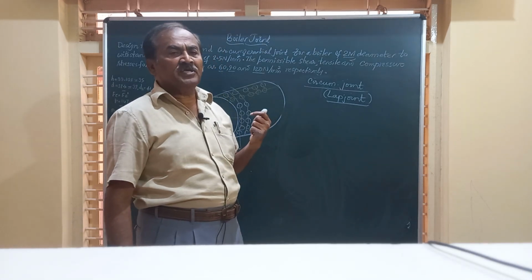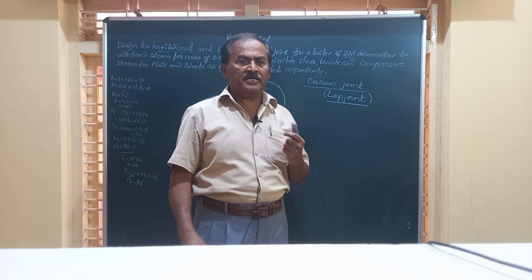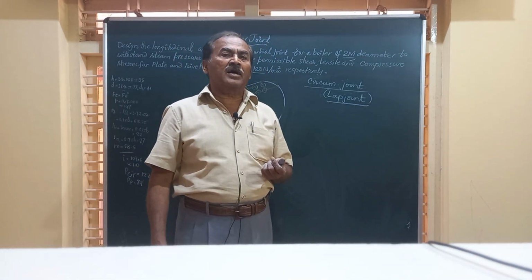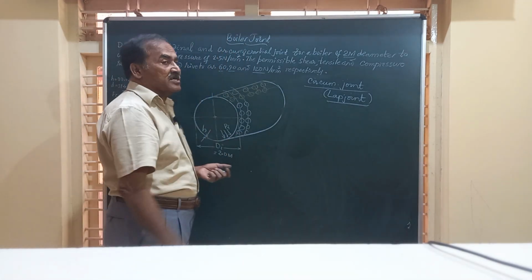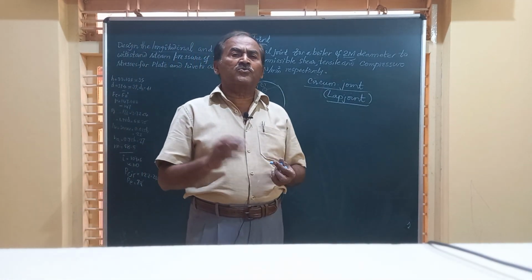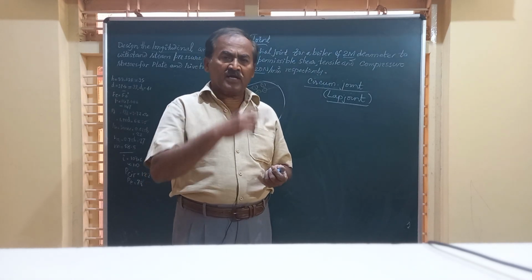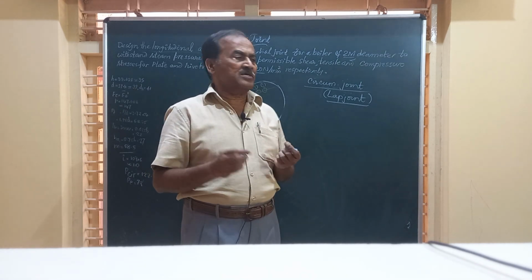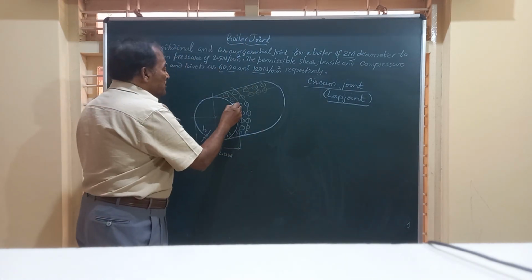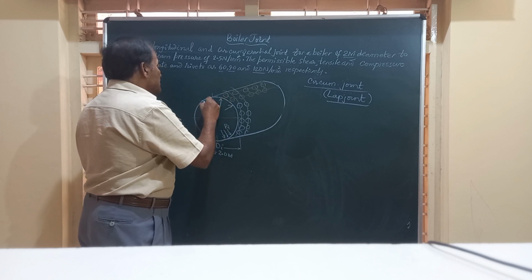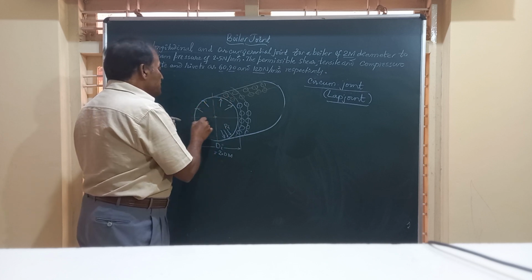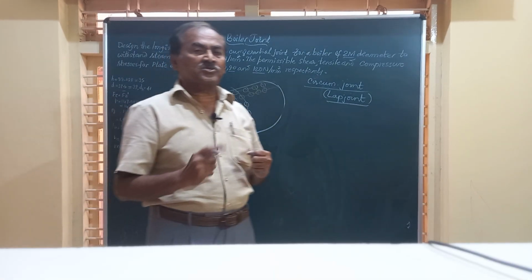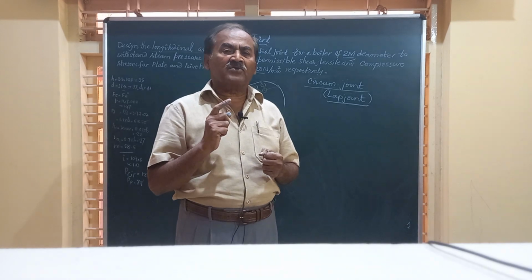So whatever value of D we have calculated holds good for the circumferential joint also. And we should know how many rivets are required. To find the number of rivets for the circumferential joint, we are going to equate the bursting load caused due to the steam pressure inside, that is PF, to the resistance offered by the rivets for shearing.